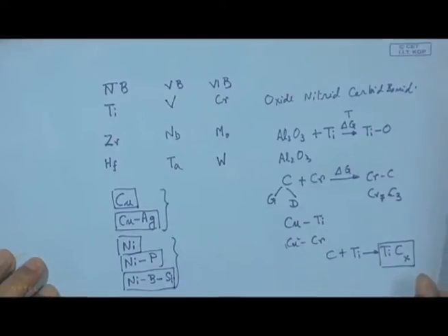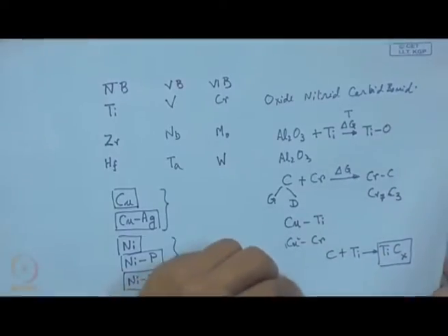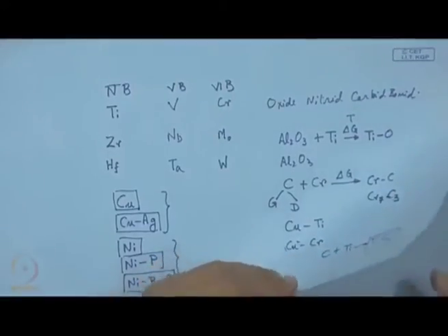Now, here the basic objective is to promote wetting, that means there will be spontaneous spreading of the liquid once it is brought in contact with the solid surface at a particular temperature, maintaining a certain environment. It can be an inert atmosphere flushed with argon, a reducing atmosphere enriched with hydrogen, or high vacuum. Under that environment it is supposed to have spontaneous spreading.